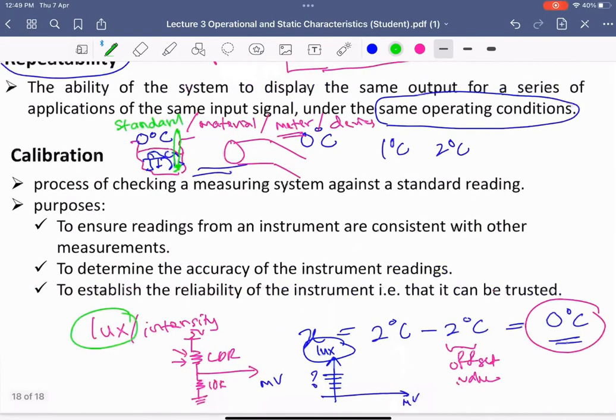Okay. So right now in your case, in the lab, in order to measure the light, of course you can buy the lux meter. That's one option. The other one is you can use a lux app from your handphone. You can download a lux app. There are many apps available because your handphone actually has a kind of sensor, the LDR, in order to measure light. When you scan something, it will give you the lux value. From that you can plot it and find the relationship between the voltage that you get from the LDR and the lux that you get from the apps. That is the simple one.